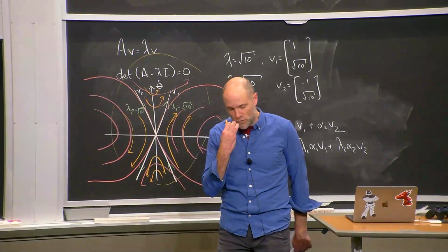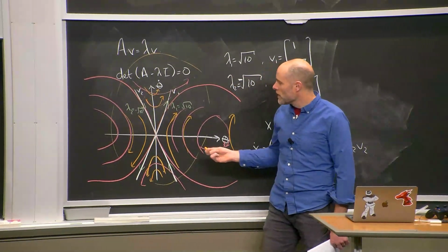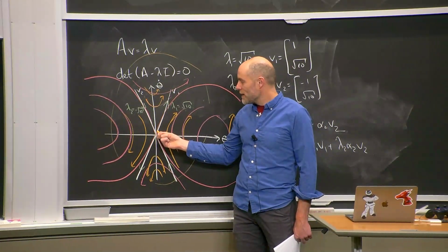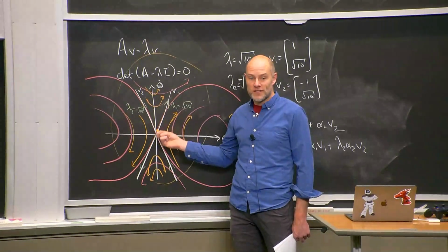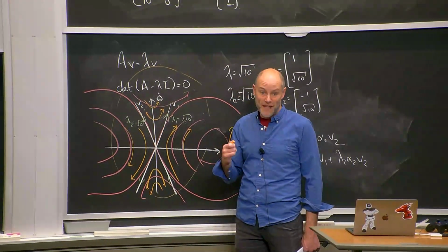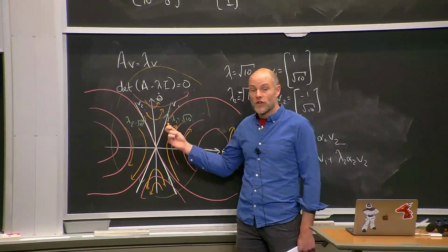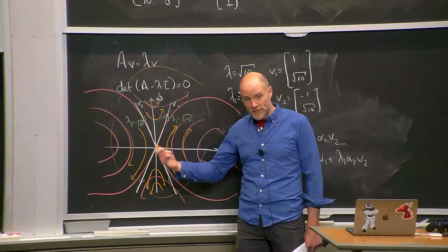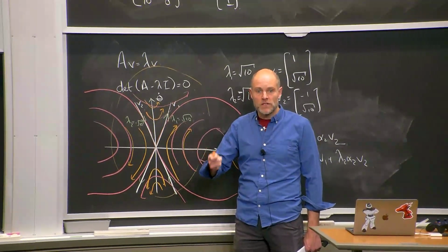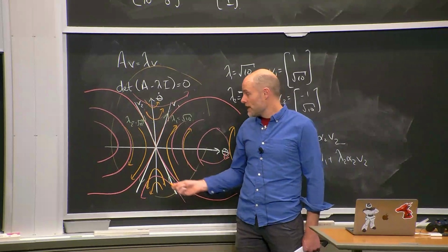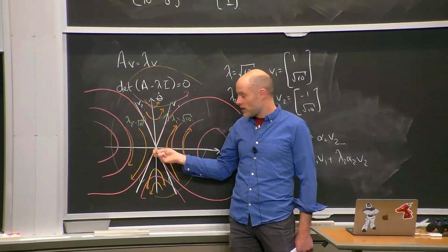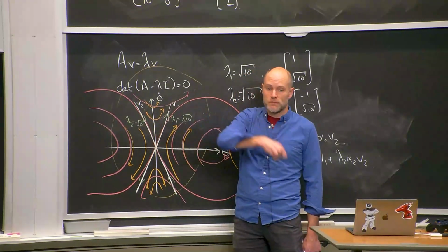Okay, awesome question. There's a lot underneath that. So the arguments roughly go like this. If your linearization is stable, that implies that your nonlinear system is locally exponentially stable also. And that is also true of the closed loop system. So if you put a linear controller with a nonlinear system and you linearize the closed loop dynamics, then you can talk about stability of the closed loop system. Assuming everything's differentiable, the stability of the linearization implies stability of the nonlinear system.